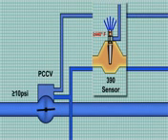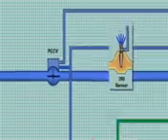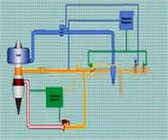When the bleed air temperature reaches 440 degrees Fahrenheit, the sensor will be fully open, causing the PCCV to be fully open. As conditions change, the sensor will change the amount of control air vented, and the PCCV will open or close as needed. If the PCCV cannot provide enough cooling air, the system can also use the PRSOV to control temperature.